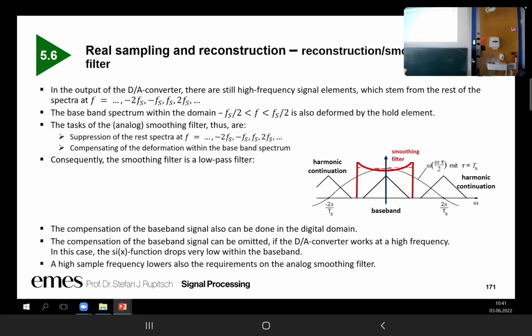And we call this effect a frequency dependent distortion. You know it from optics, perhaps from fiber light guides. You have an input signal that is a very small rectangular pulse, then the output will be something that doesn't look like a rectangle anymore. This is the effect of distortion, or dispersion. And also in case of filters, we have this dispersion problem. In the digital world, we build up FIR filters. With such filters, you won't have this problem anymore. But this is a topic for later.